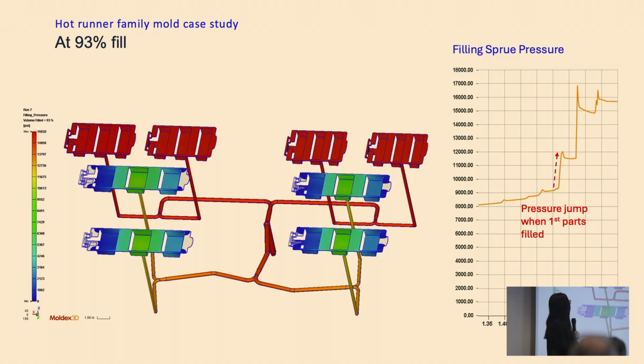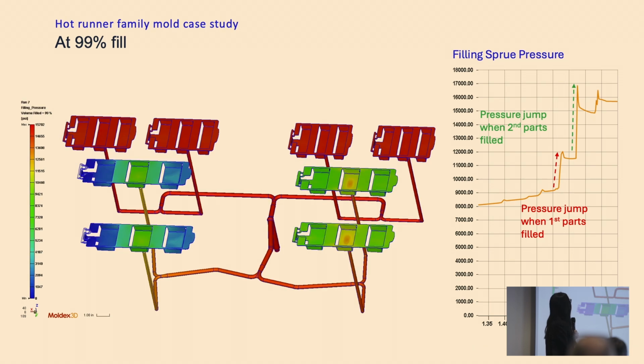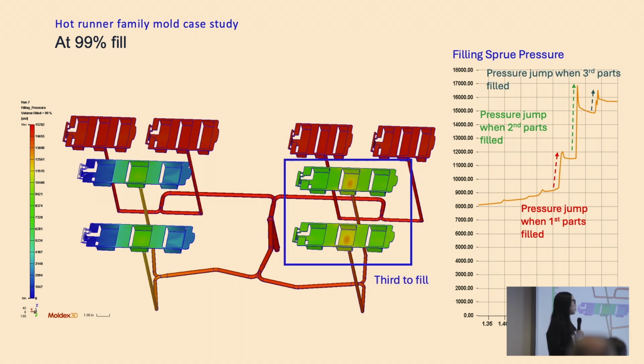So it's also quite obvious. We go a bit further. At 93% filled, the second parts are filled, and again, we see a pressure jump. And at 99%, the third heaviest parts are filled, and we see a third, smaller pressure jump, but still a pressure jump. So every time the cavity is filled, you observe a pressure jump, which not only indicates a